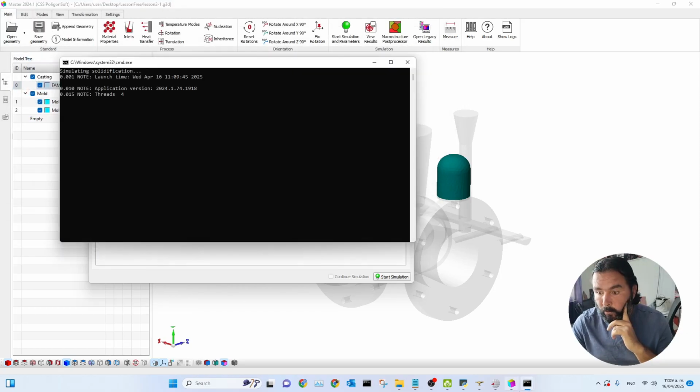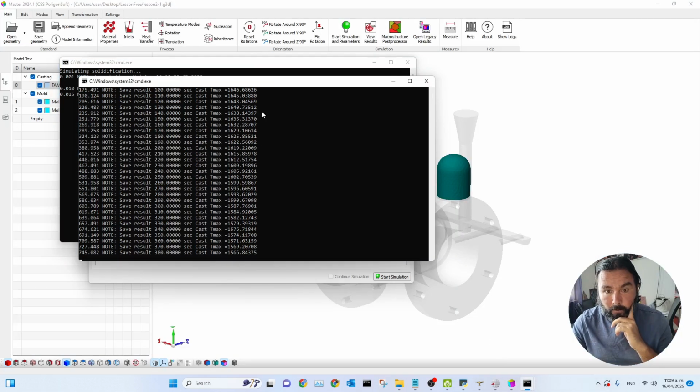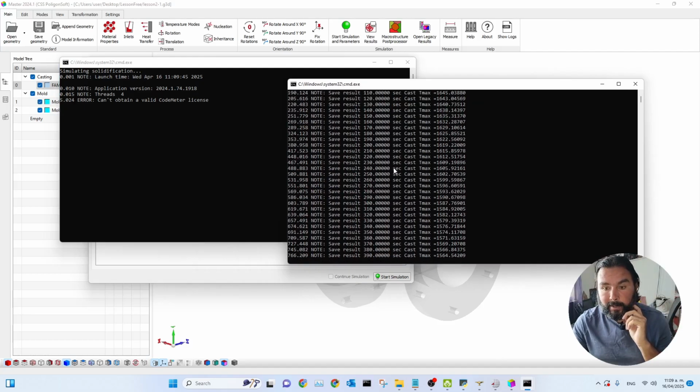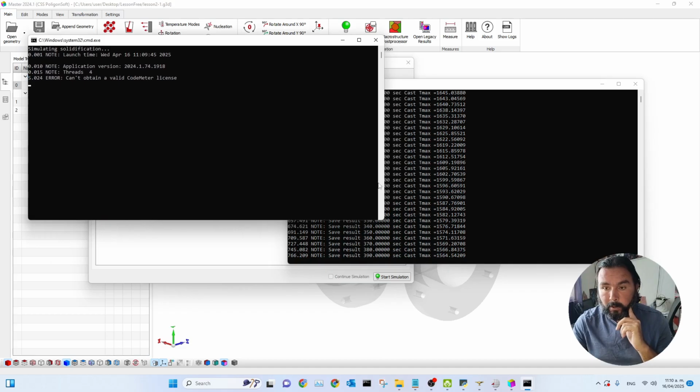Here I run a second calculation, and what did I want to talk about here? As we can see, the program, without any problem, even though we have set 4 cores for the first calculation and 4 cores for the second, and today on my computer I only have 4, the program doesn't limit this in any way. We can run calculations in parallel, and they will coordinate among themselves how much computation to use for the first calculation and for the second calculation.